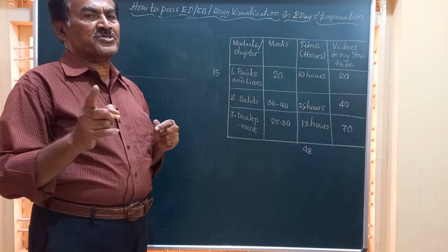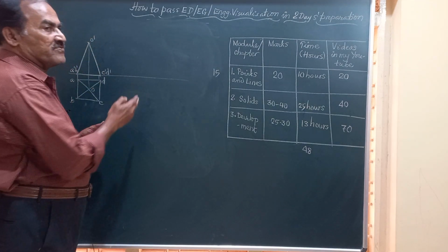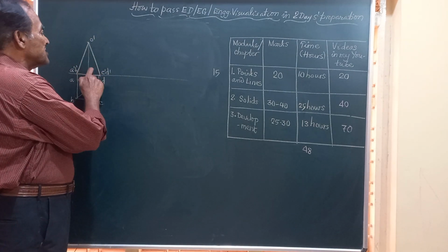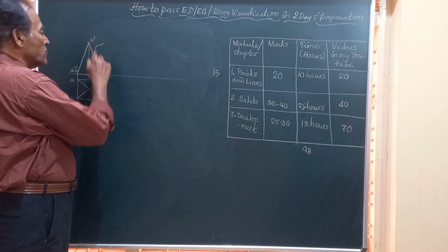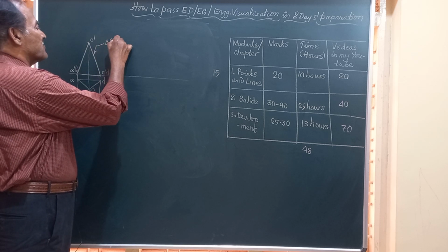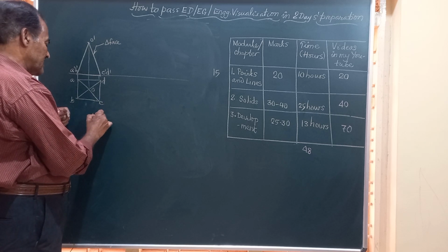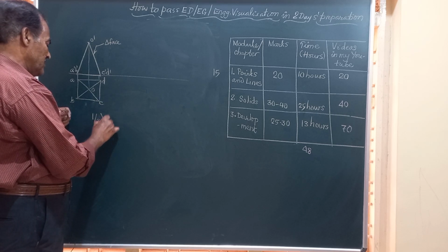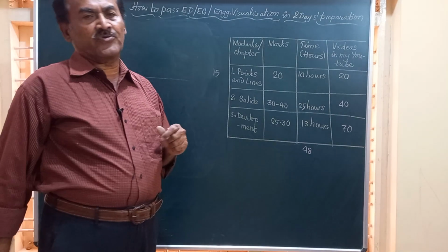Friends, if it is a question on a square pyramid resting on triangular face, this is the correct position, because in this position, this line O dash, C dash, D dash represents one of the triangular faces. So once you write it correctly, you get one third of the marks. One third, maybe like 12 marks, is assured to you.